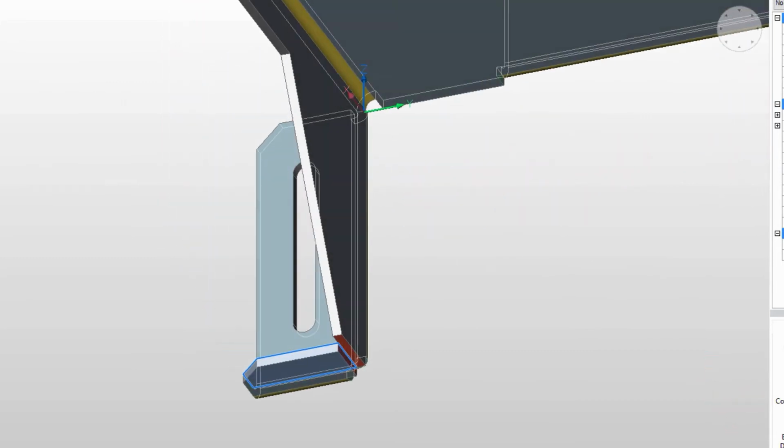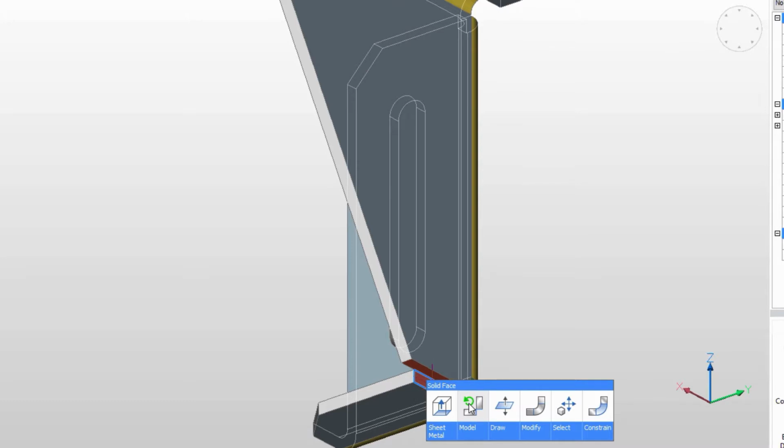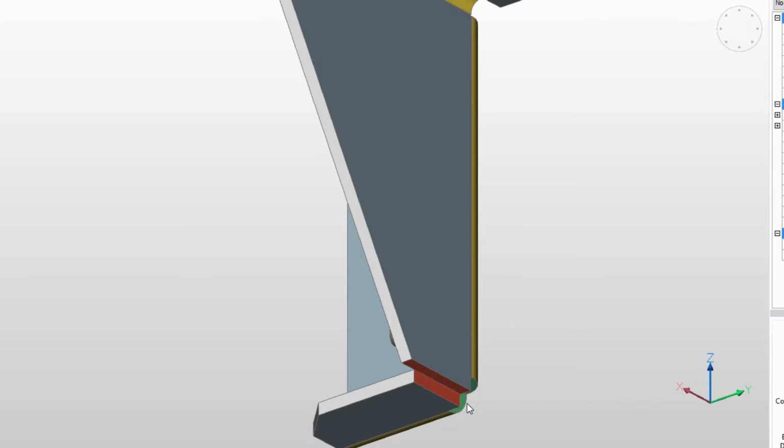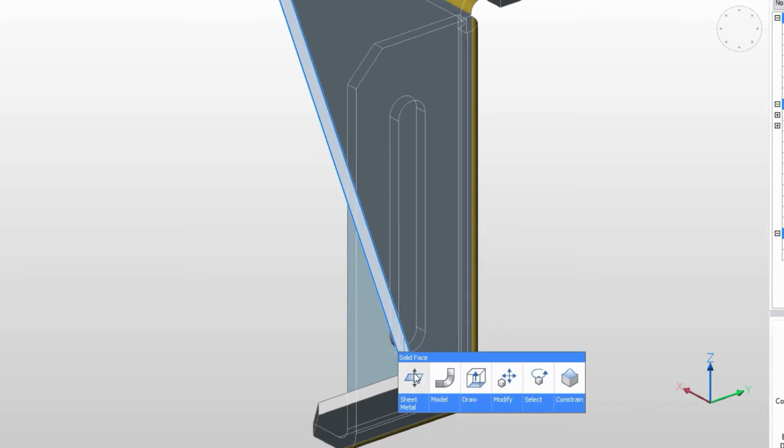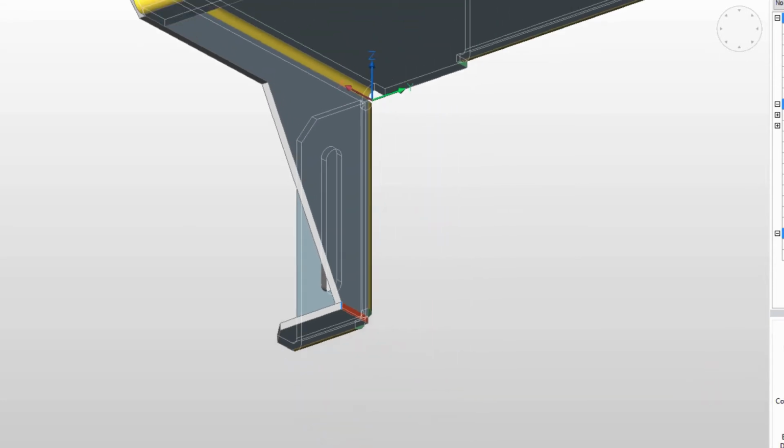These two flanges should meet with another connection type. To realign the side faces of the junction, hover over one of the junction faces and use SM Junction Switch command. And again, the BricsCAD quad cursor puts the right commands at your mouse cursor.